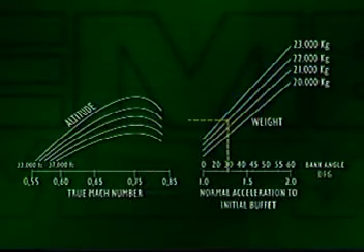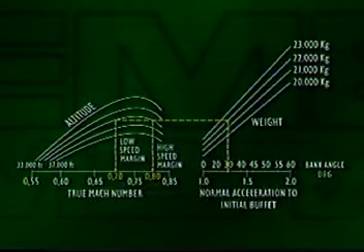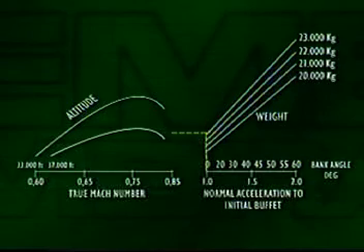At a given altitude and weight, there is a low-speed and a high-speed buffet boundary. In the example shown, there is a certain range in which the airplane can operate. The low-speed buffet is supposed to occur at Mach 0.70. If the aircraft accelerates to Mach 0.80, high-speed buffet will set in. The higher the altitude, the smaller the speed range between high and low-speed buffet. The lower the altitude, the greater the speed range.